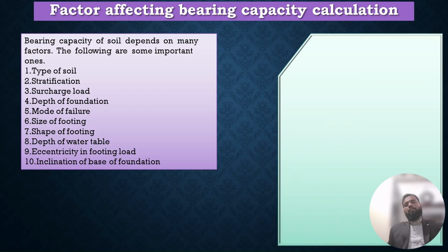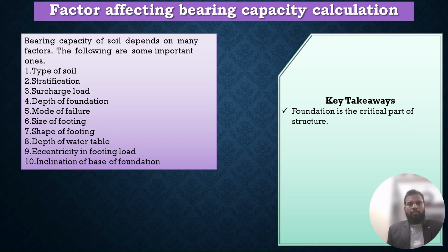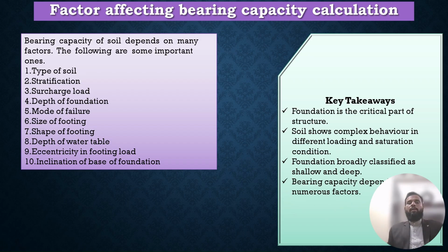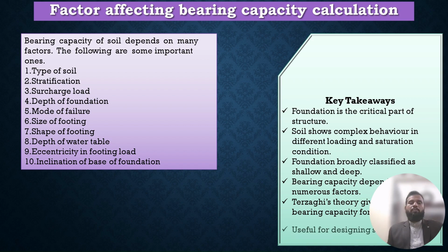The key takeaways from this class, to summarize what we have learned: foundation is a critical part of a structure. Soil shows complex behavior in different loading and saturation conditions. Foundations are broadly classified as shallow and deep. Bearing capacity depends on numerous factors, and Terzaghi's theory gives the bearing capacity of a stiff footing.